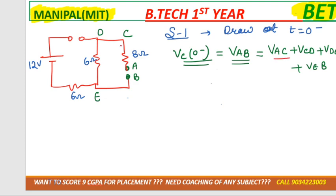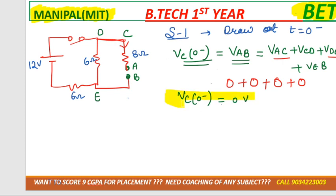AC, no current is flowing because it's open circuit, 0. CD, no resistance is there and no current is there, 0. DE, as you can see, again it's an open circuit, so no current will flow across 6 ohm as well, 0. VEB, this is also 0 because no resistance, no current. So ultimately we got VC of 0 minus is equal to 0 volt. Up to here we have completed our step number 1.